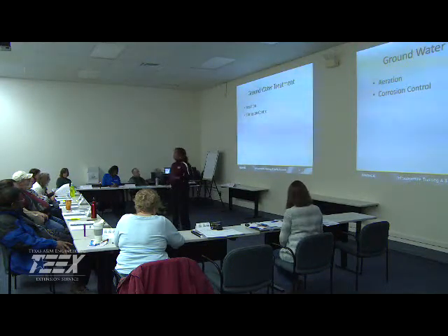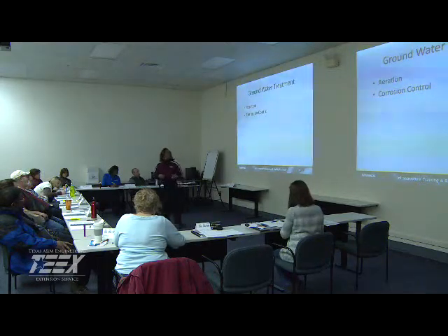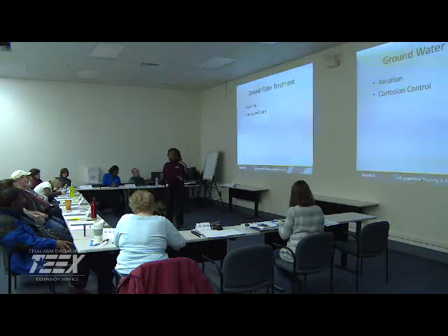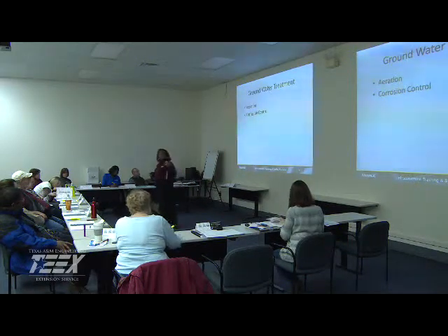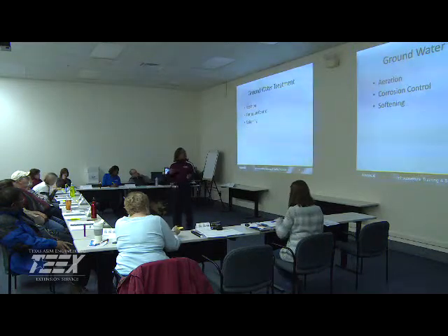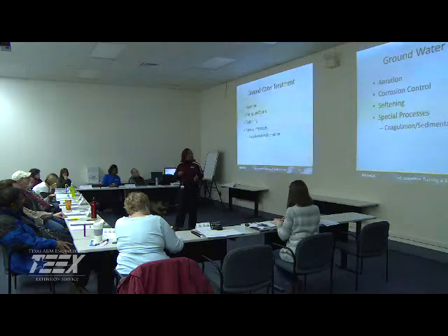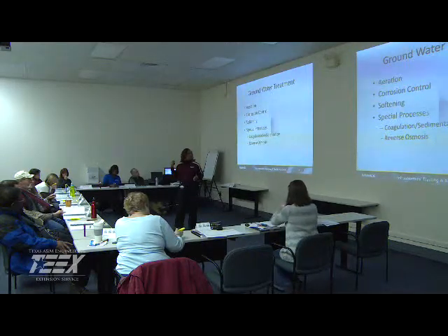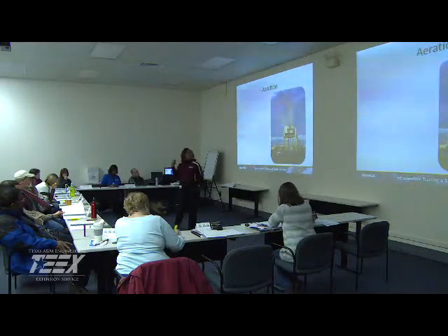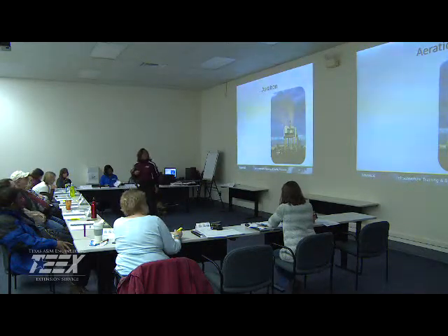So some of the common treatment techniques, now that we've established that, would be aeration. If you have gases and things like that, excellent. Corrosion control, if you have corrosive water. Softening. There may be special processes such as coagulation and sedimentation, reverse osmosis. So let's look individually at what each one of them will take care of.